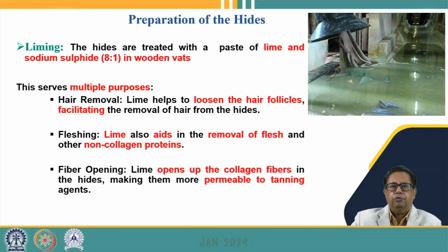Then we go for the fleshing process. Here the lime also aids in the removal of the flesh, and it also helps in the removal of the non-collagen proteins which are there in the hides, so that the hide becomes free from these materials, and later on we can go for the tanning process. Similarly, it also opens up the fibers, where the collagen fibers become more permeable to the tanning agents which we are using during the tanning process.